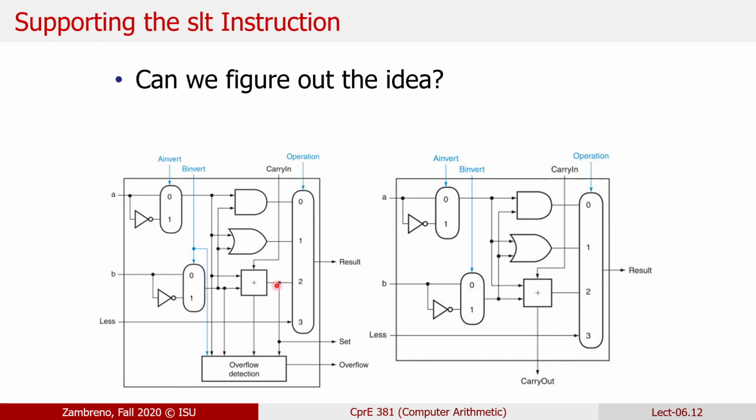for this output of the actual add operation, we're now using it for two purposes, only in that most significant bit of our adder. We're using it potentially because we may just want to have done an add or subtract operation, and now we're also using that bit, and we're going to call it set. Or you could also have called it result of subtraction or result of operation is negative. It depends how literal you want to be. We're only using it for set less than, but that's what that bit is specifying. Is the result of whatever we added together negative or not? Because that's only in that most significant bit that we're doing that here.